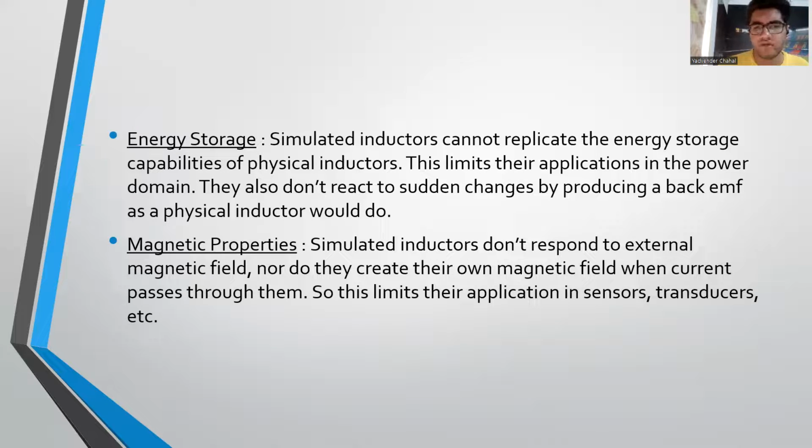Talking about energy storage, simulated inductors cannot replicate the energy storage capabilities of physical inductors. This is a drawback. This limits their applications in the power domain. They also don't react to sudden changes by producing a back EMF as an actual inductor does. Magnetic properties of simulated inductors don't match up as well. They don't respond to an external magnetic field, nor do they create their own magnetic field when current passes through them.